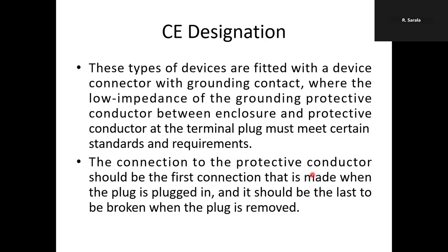The connection to the protective conductor should be the first connection made when the plug is inserted, and it should be the last broken when the plug is removed.